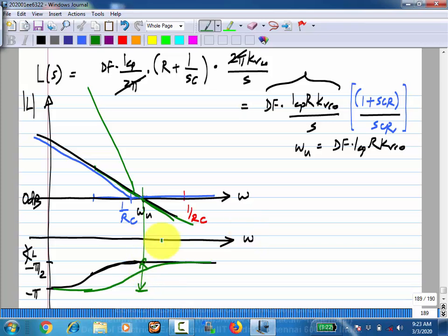So that goes on reducing, and then if you make C very small, then your loop gain will be like that. Okay, and your phase will look like that, and your phase margin will be really poor. As usual, when I say C is large, I mean it's okay for casual conversation. Finally, you have to say it has to be larger than what? That is true of any dimensional quantity, right? So in this case, essentially C has to be large enough so that you have adequate phase margin in the loop. Okay. The intuitive condition that we had got, that it should settle before this starts acting on it, is translated to this one.